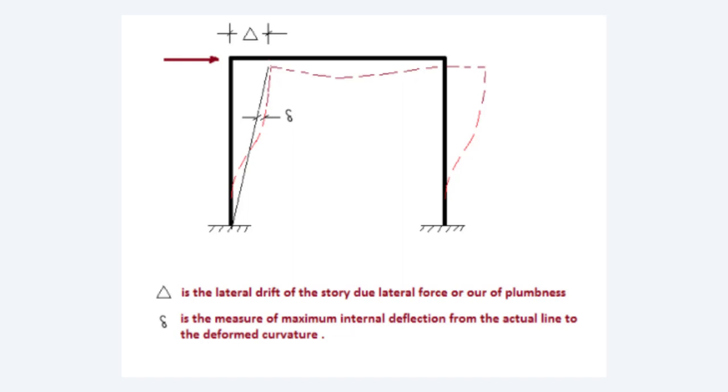So in short, no axial member in a real-life scenario is perfectly or ideally straight. Perfectly straight members we only model in the software, right? But in real life, that doesn't happen. There is always some proportion of initial imperfection, like crookedness or curvature, which can add the initial second-order effect to trigger the P-delta solution. This solution could eventually tell us if it is converging or diverging. If it is diverging, then we can understand that the system has already buckled.